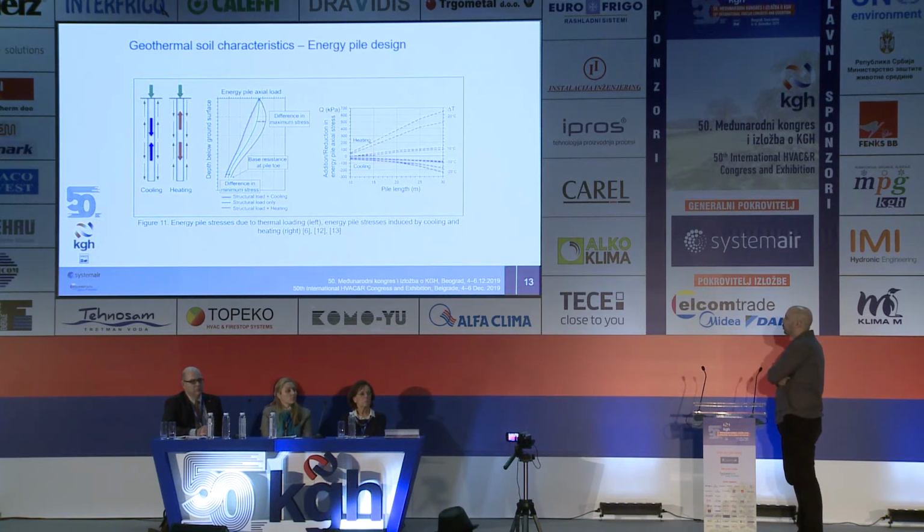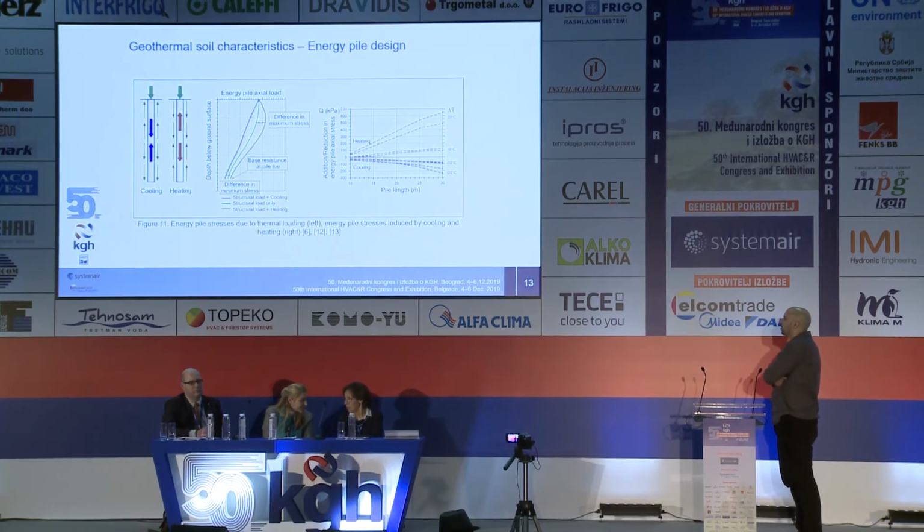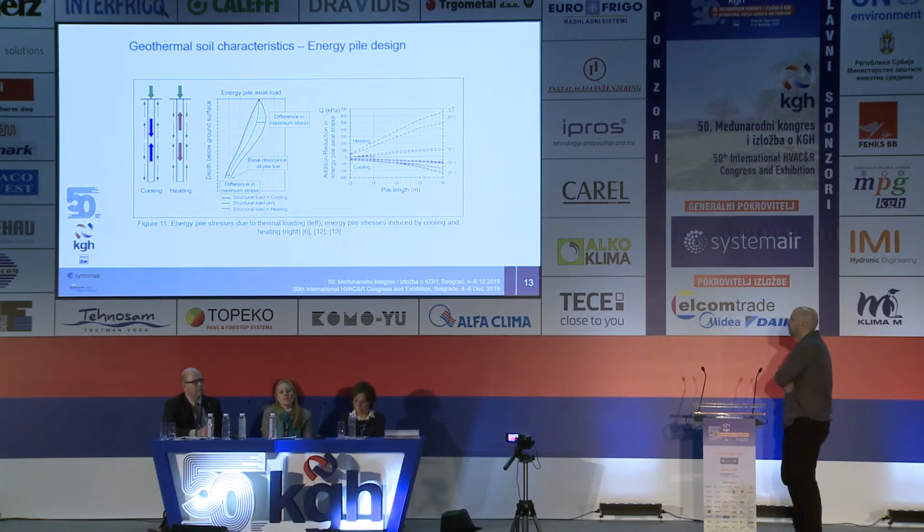What can we conclude from this diagram? Well, we can see that structural load plus heating of the element induces a bigger axial load, while structural load plus cooling of the element induces, how can I say it, lesser forces in the pile.